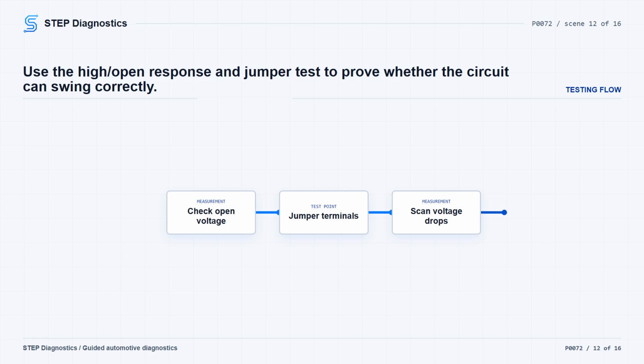If voltage data is not available, check for the circuit low fault to set with the jumper in place. If either result occurs, the temp sensor is faulty. If the voltage does not change to 0 volts or the circuit low fault is not present with the jumper in place, check the resistance of the temp sensor signal circuit and temp sensor ground circuit. Typically, the circuit resistance should be less than 0 ohms.